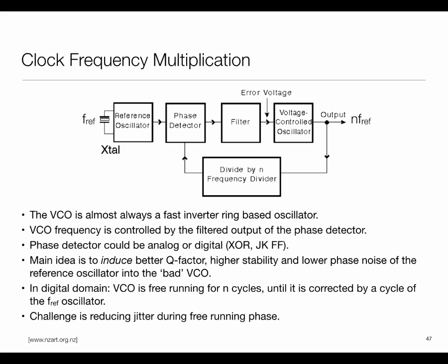If you look at any processor, including the one on embeds and all, you would see that they have a pretty elaborate clocking subsystem where you can program them, you can set the frequency at which your processor is operating. You can select what the source is. You can say it is a crystal oscillator or some other source, external or internal, and all those kinds of games can be played.